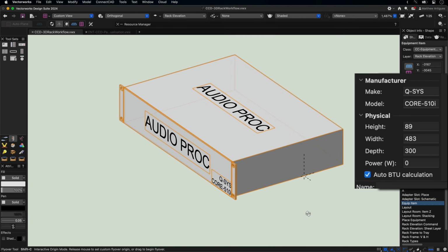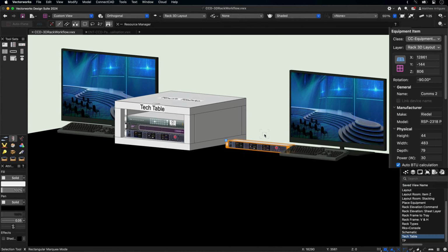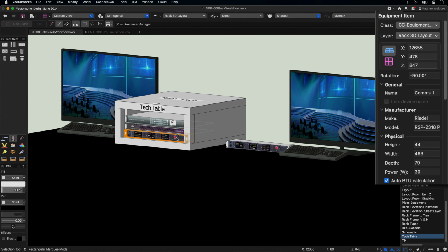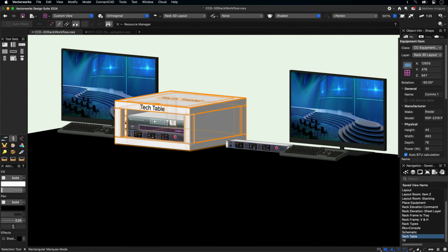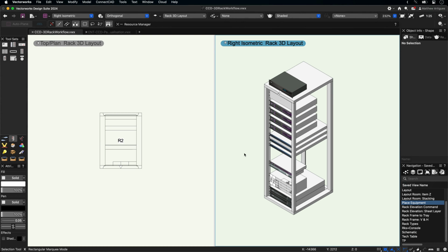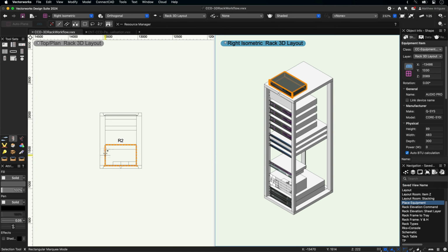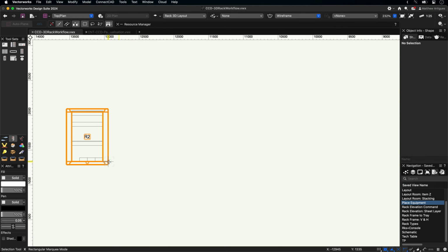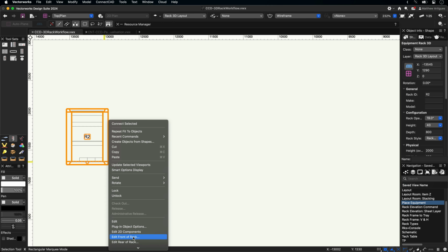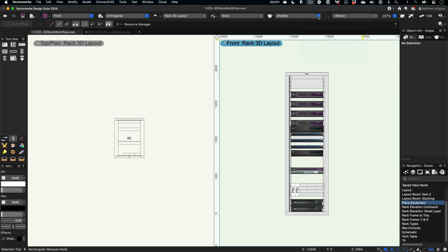Equipment items are represented as 3D parametric objects and contain all the necessary dimension information in the device's symbol definition. When placing the equipment, the preview will rotate dependent on whether you are floating over the front or rear of a rack. The equipment will be placed in the nearest rack unit position available. You can also use Edit in Multiview to mimic the 2D drag and drop workflow.